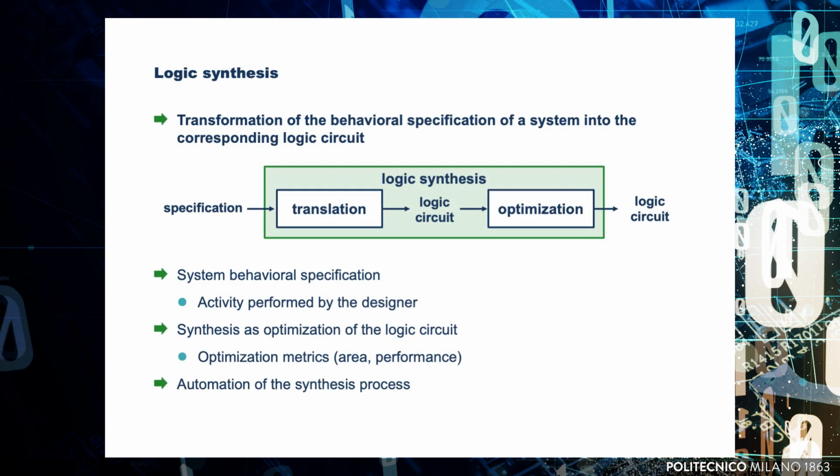Returning to the title of the series, let us pose another question. How are logic circuits designed and implemented? The process of implementing a logic circuit is called logic synthesis. More precisely, logic synthesis is the procedure that takes as input a behavioral specification of the system to be implemented and produces as output the logic circuit that realizes such behavior.